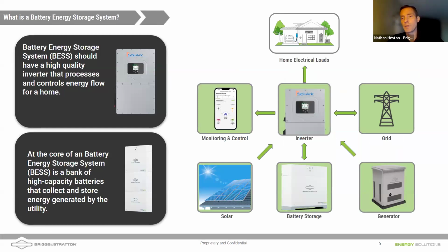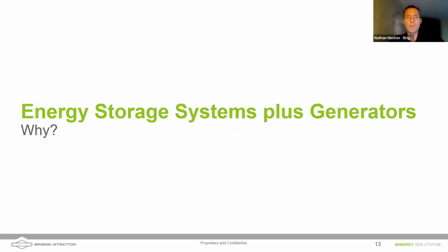And with 400 amp service, I doubt a single inverter, which is capable of 12 kilowatts, would really cover the home's load. So you would want to use 2 inverters, or you might want to split off some of those loads that you don't want in a grid outage situation. So great questions. Keep them coming.